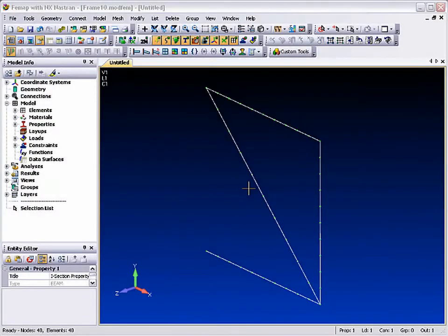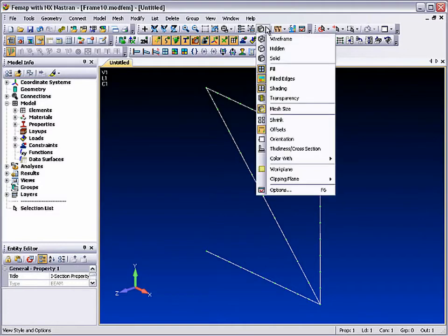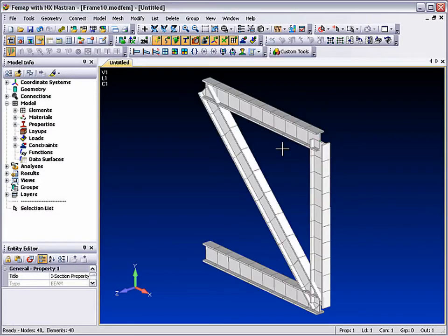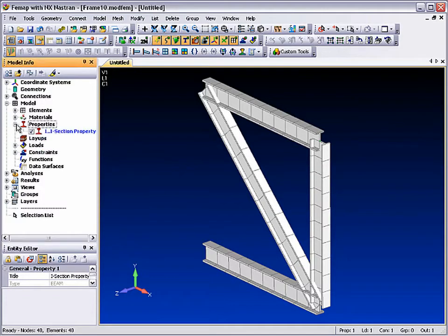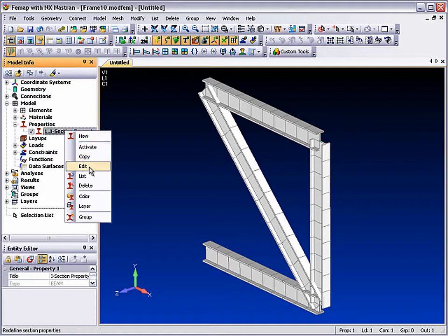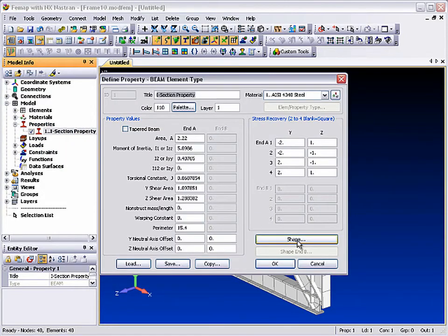Beam elements are a very powerful way of simplifying the modeling of long and slender components in the design. However, as one-dimensional elements, beam visualization can be difficult. For post-processing, many solvers require you to define the points of interest on the cross-section where data will be recovered